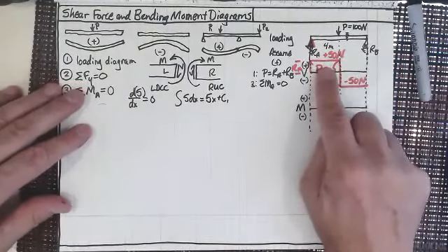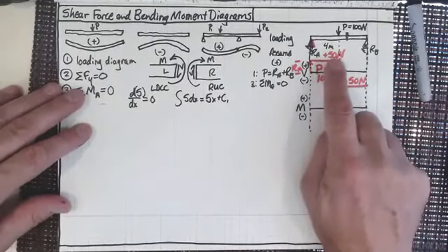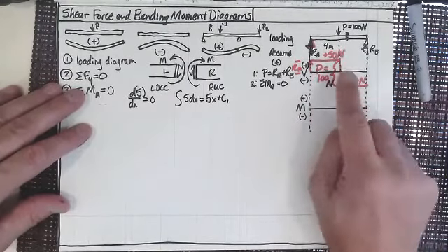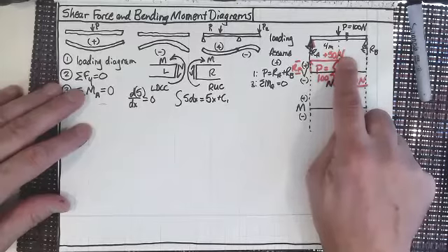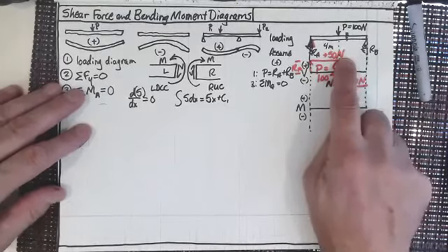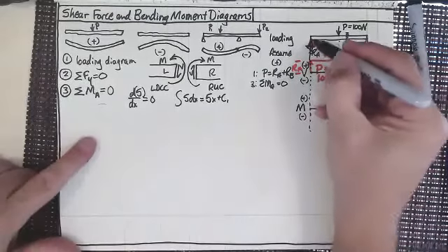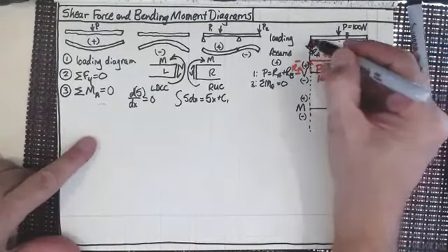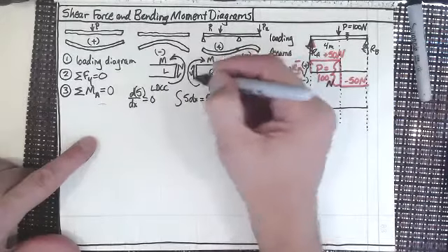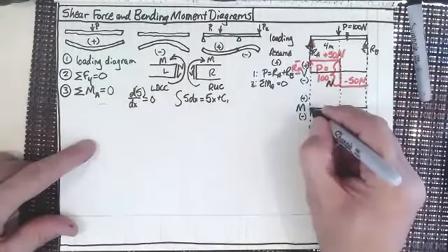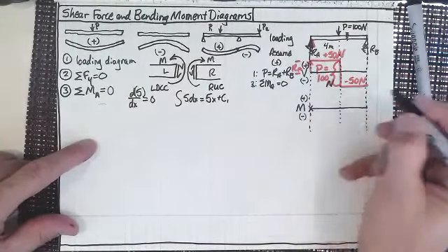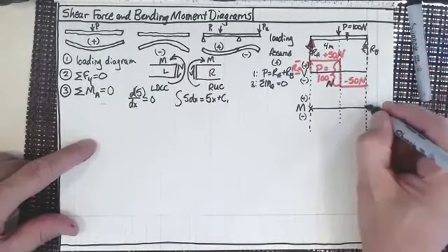And so if we look here, we know that the slope of the line is going to be 50 newtons per meter, right? 50 newtons per meter. We also know at a simply supported beam, if I were to take it all the way to the end, the moments are 0. So the moments have to be 0 here. They have to be 0 here.